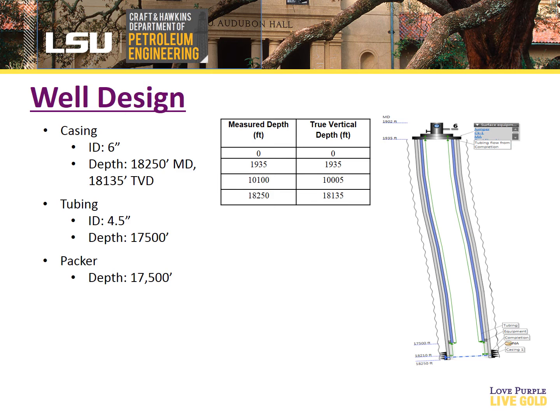All values corresponding to the reservoir were entered, and we established our fluid model as black oil. In order to form open hole completions as requested for the base case scenario, we set the rate dependent skin to 0 and input our calculated skin value of 3.02 for mechanical skin, completing the well component of our model.